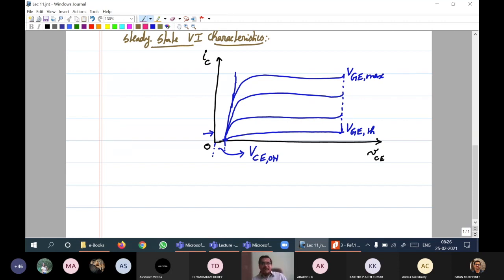The fall in voltage, the two fall times, in an IGBT those two fall intervals will be longer. That's all. That is the only difference. Principle wise, it is the same. Capacitance effect causes the current to rise gradually. Threshold voltage should be set up. Gate capacitance should be fully charged. Only then the conduction, everything is going to be exactly the same.